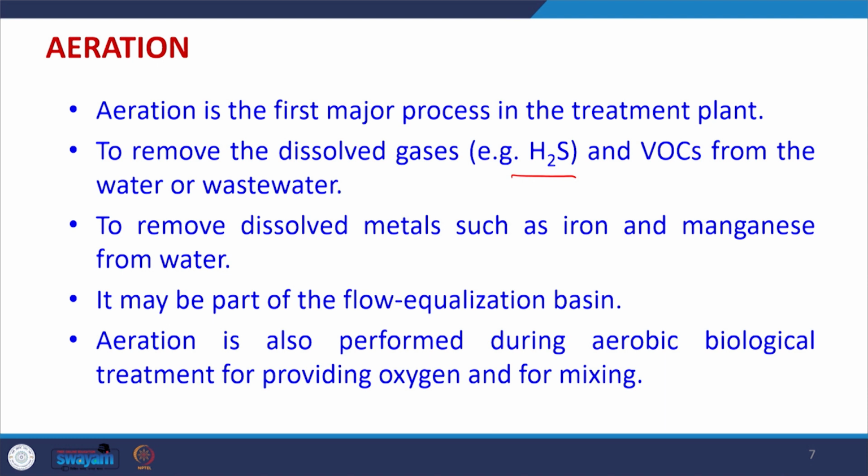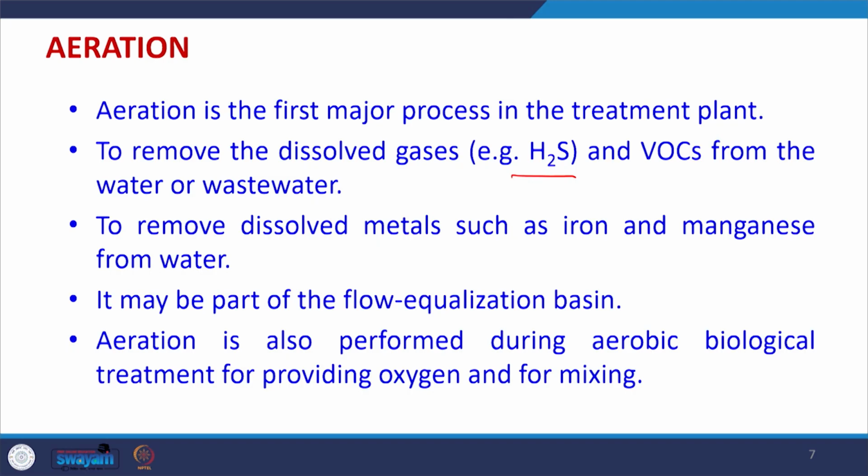Now, we will study aeration in greater detail, and it is not only used separately, it is used along with the biological treatment where the aerobic treatment processes are being performed. So, that is why aeration is not only important as an individual unit, it is also an essential part of all aerobic biological treatment methods.